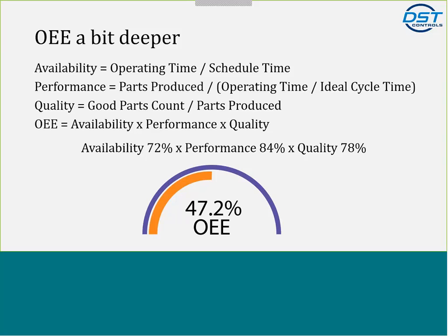But just to give you a reference, world-class companies that live and die with OEE and have lean manufacturing, if you get into the 80s and 90s of OEE, you're doing remarkably well. So an honest OEE number that's above 50%, I think, is doing pretty good, and typically you'll see numbers below that. So just remember, this is a multiplication, not an average.